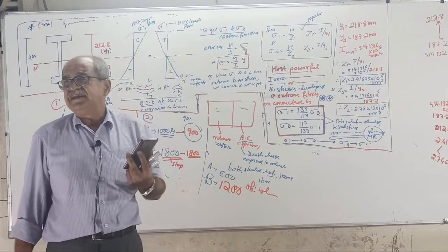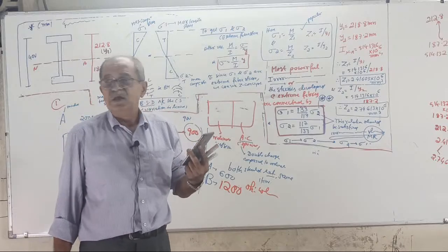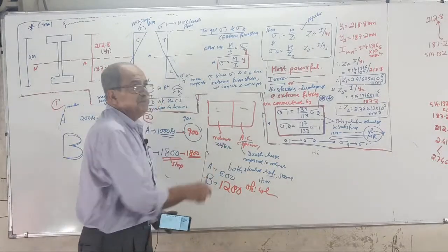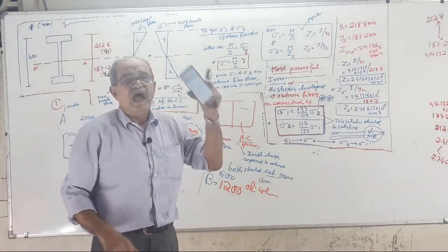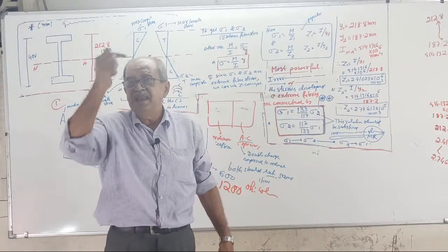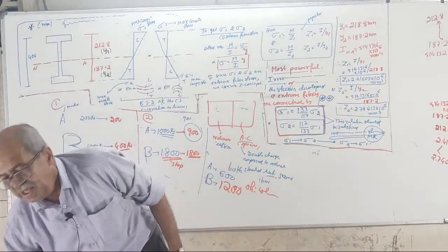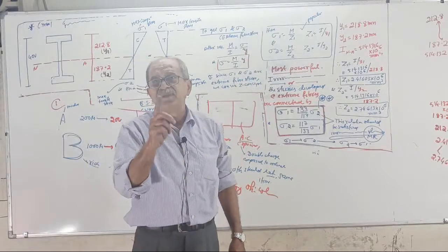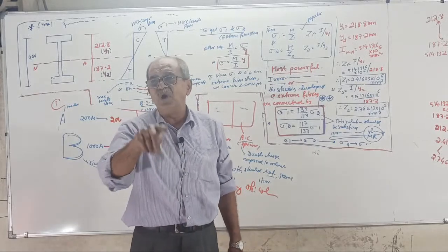600. How much at that time B has to pay? Or how much bill B can go up to? How much order B can go for? 1,200. When the bill for A reaches his money in his pocket, at the same time bill for B will reach his money in his pocket. When the compressive stress in concrete reaches the permissible limit for concrete in compression, at the same time tensile stress in steel will reach permissible tensile stress for steel.